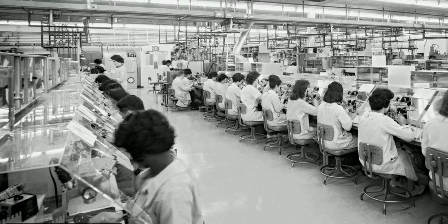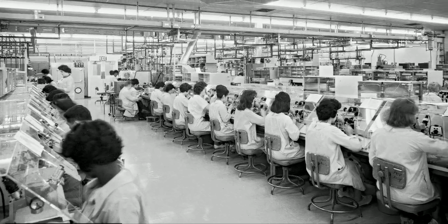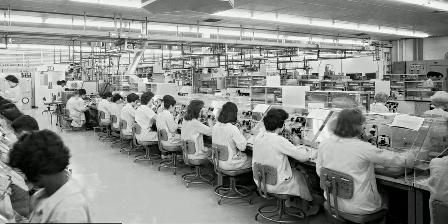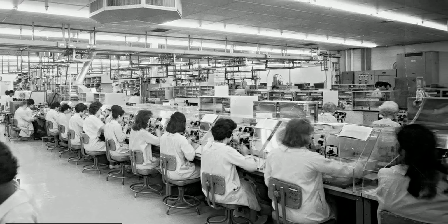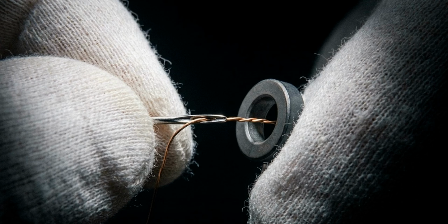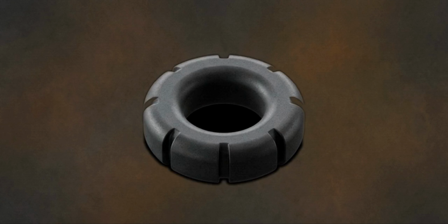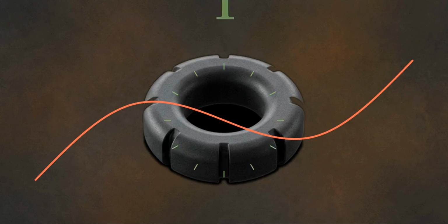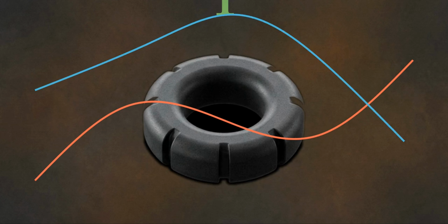Manufacturing took place at the Raytheon plant in Waltham, Massachusetts. They recruited local textile and watch factory workers, women possessing the extreme fine motor precision necessary to weave the memory by hand. The data was hard-coded by physical routing. A sense wire passing directly through the center of a magnetic core registered as a 1. If it bypassed the outside of the core, it read as a 0.